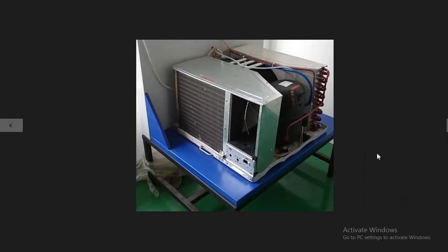Okay, so we have this demo along with us where I can see a normal window AC. I think its capacity is around 2 ton, or 1.5 or 2 ton. I'm not so sure. I've never checked it. But the main illustration behind this photo is that now we can see the components, right? So here there is an evaporator. Here there is a compressor. From the compressor, a red line goes into the condenser. Then the outlet of the condenser goes into the capillary tube, and from the capillary tube it will pass inside this evaporator, and the output of the evaporator, which is this blue line, will go into the compressor. So this is how the circuit has been completed.